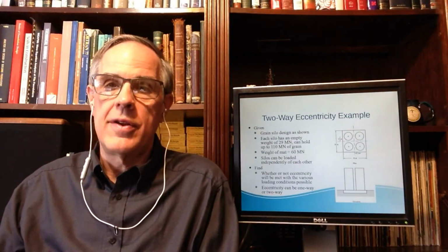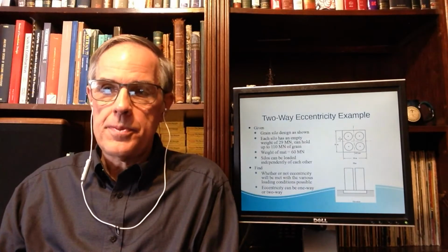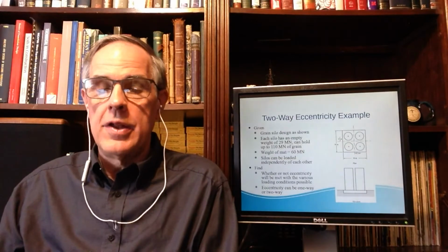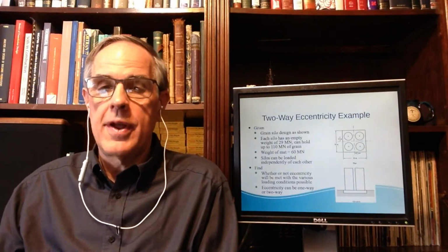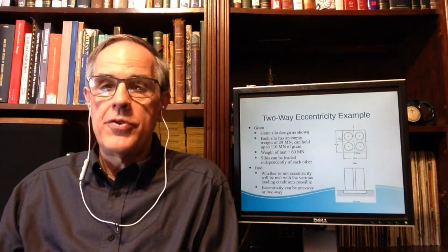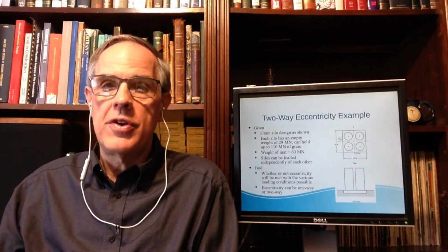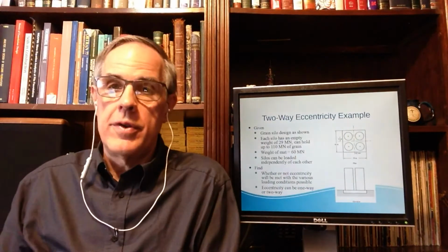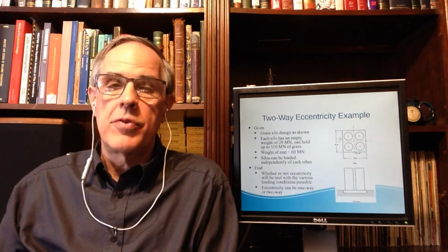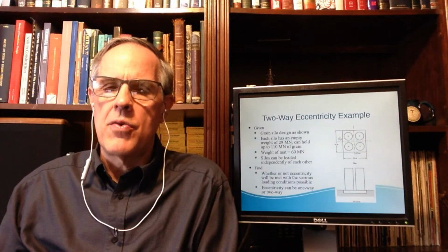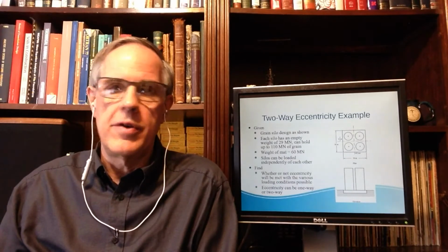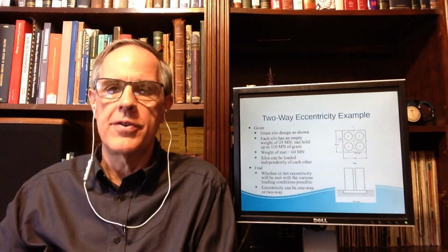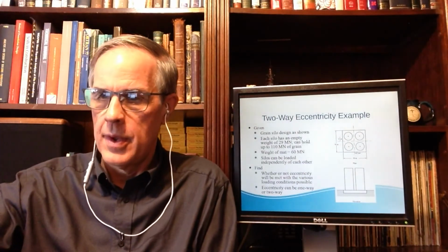That's going to result in a concentric load. Obviously, loading all four of them will result in a concentric load. The two that we're going to take special interest in is we load them on one half over here, or we load one in the corner. Obviously, 3/4 is going to give us not quite a concentric load, but a more concentric load than just loading this one or this one. The two worst cases are those, and we're going to talk about those.